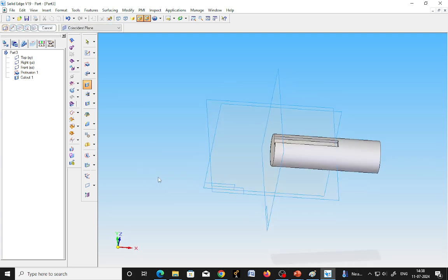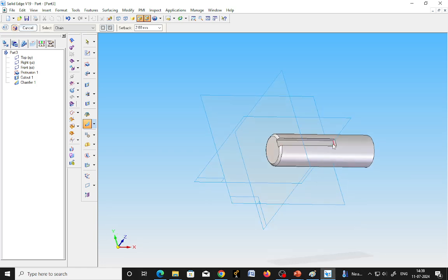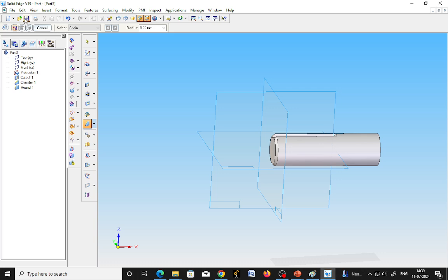Got it? So, now let us make a chamfer. Whether chamfer is going to work over here. Okay. It is a 2 into 45. Let us go for 2 mm. So, you need to make a fillet of the same radius. How much depth is provided here? Depth is provided 4 mm. Let us go for radius as 4 mm. Okay. Shaft is over.